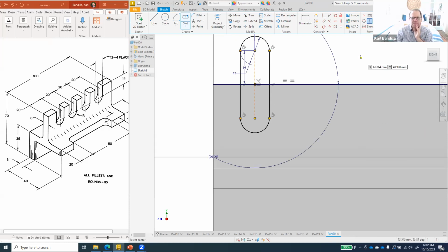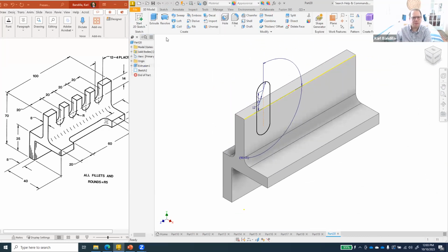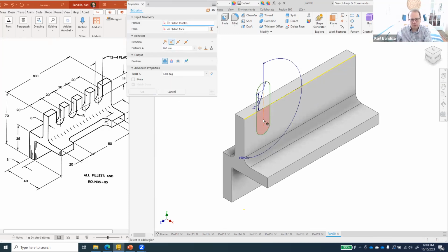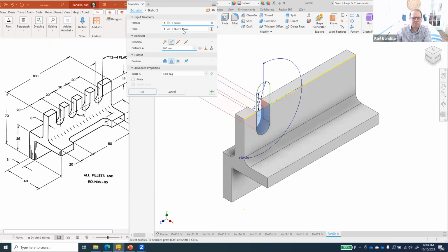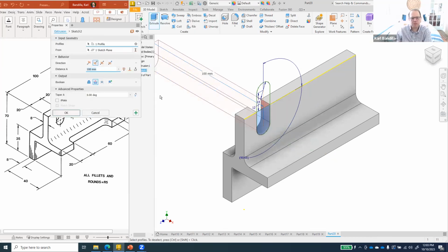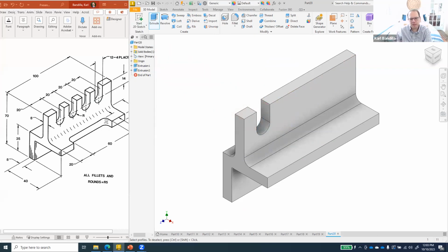That looks about right. Now let's make sure that we have this correct. This should be 12. Okay, good. So in this case, we chose the right option. We could actually just leave it like that. I was going to say we need to cut this and trim it, but in the end we don't need to because there's nothing else that we'd be cutting up there. So we can do extrude. It even chooses only half of the one, so that's perfect. It doesn't matter how far back we do our extrusion because there's nothing there that we could break. And there we have our first tooth.